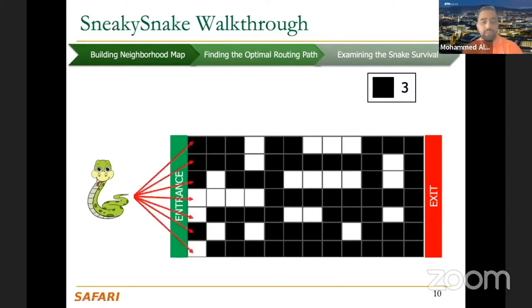So how do we solve it? It's very similar to the single net routing problem. In each row, you detect how many steps you can go further. So you find 0 steps here, because you start with an obstacle or a module, so you cannot pass. Here you can move 4 steps forward, because your goal is always to go from left to right, so you want to go as far as possible in each row. That is a greedy choice to get the shortest path. Because if there are no obstacles at all, then you just walk in a single row and that's it.